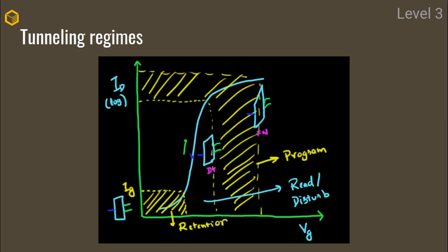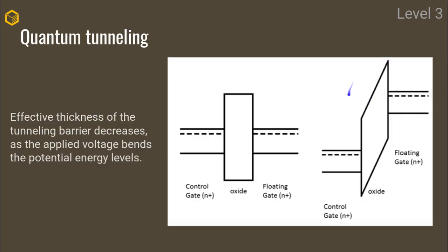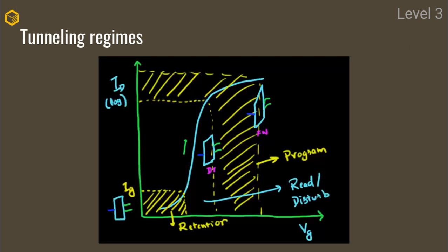But what really interests us is, you can see this goes up really fast, and it's this last regime which we call the Fowler-Nordheim tunneling regime. Where I would be in this latter regime, my particles would be under a big enough voltage differential, and so a big enough field, so that they can tunnel through. And so basically, this would induce charges being able to flow through my source and my drain.